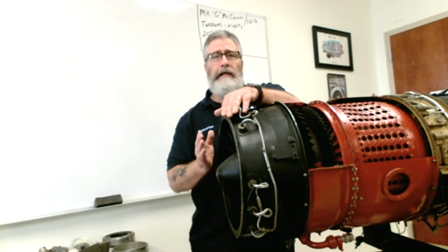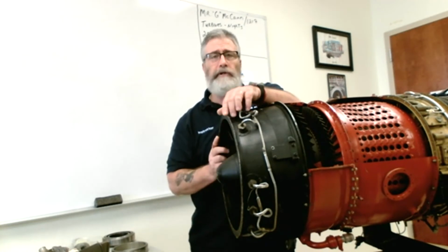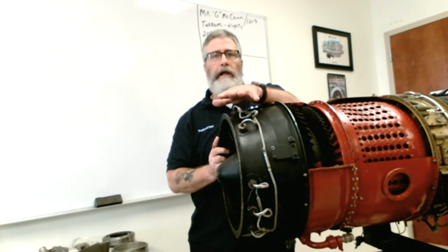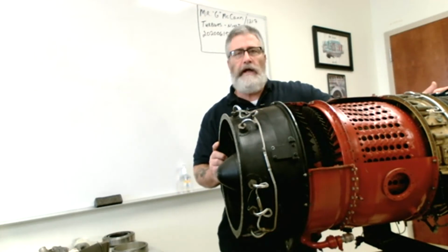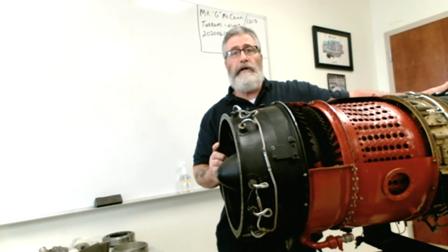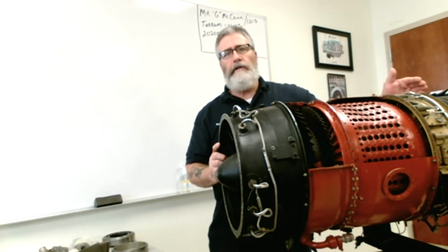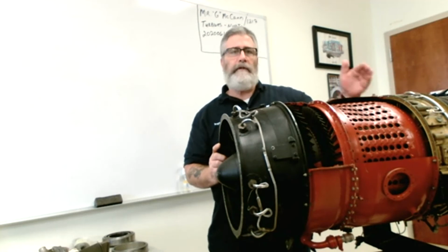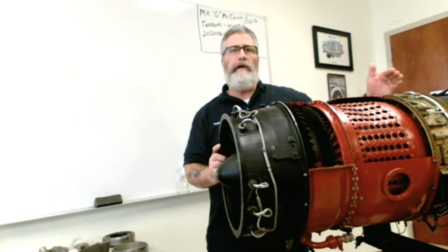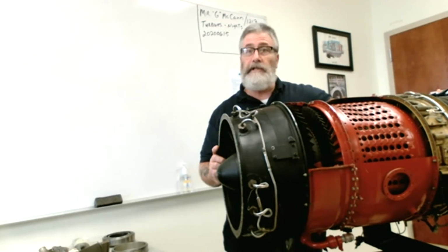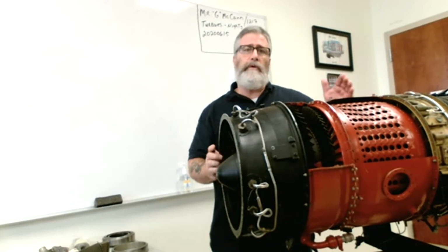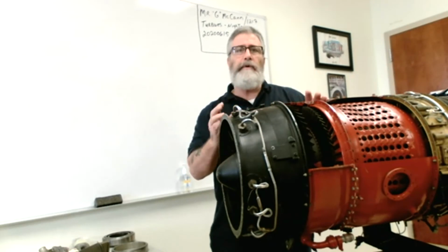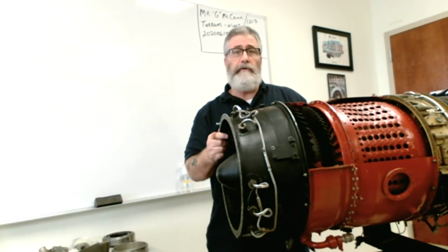So the only exception to that is supersonic aircraft, mostly military aircraft, all right? There's a couple of things you need to know about that. First of all, aircraft, as they're flying, whether they're flying sub-Mach or supersonic, the inlet design has to be such that the air entering the engine must be below Mach 1. That's an absolute, right? The engine cannot support supersonic air coming into it. Now, they do that through the inlet design or something that's called variable geometry on the inlet design, which means that the inlet might actually change in shape mechanically to adjust to different speeds.